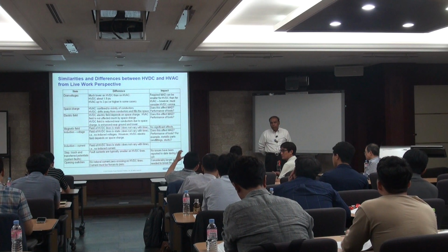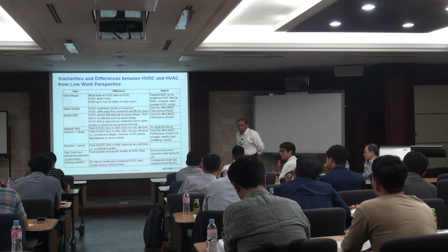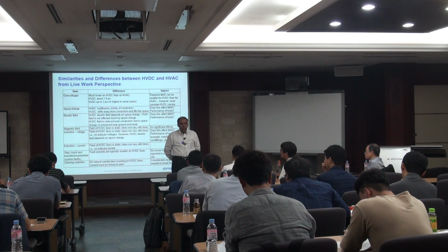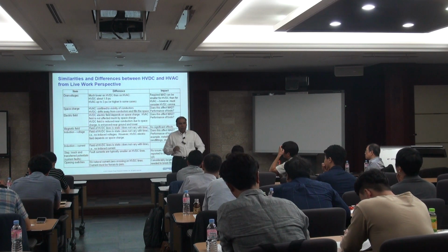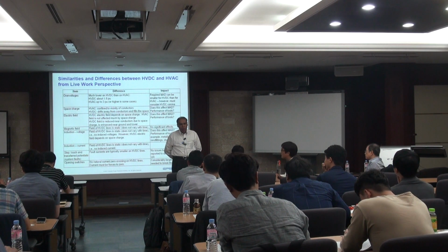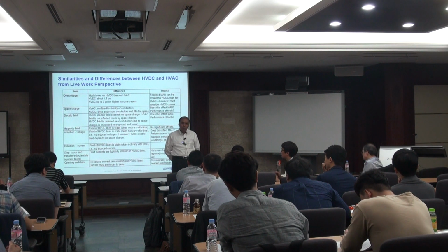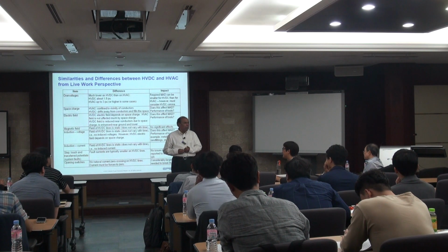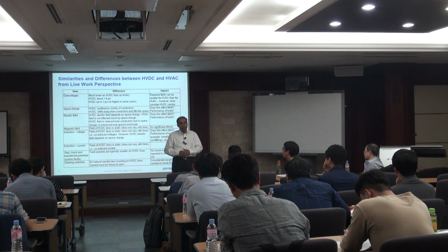In case of the AC system, if there is more bundle, there's less corona. Exactly, that is another thing also. You can design your number of conductor bundles to meet your corona performance. That is the main design criteria. John is going to talk about it tomorrow. That's why, after tomorrow's presentation, you will understand more. Then you can ask more questions on this. Those will be covered tomorrow.